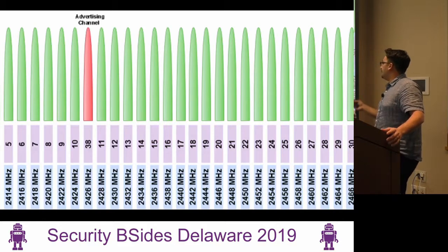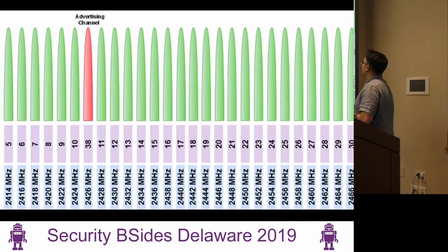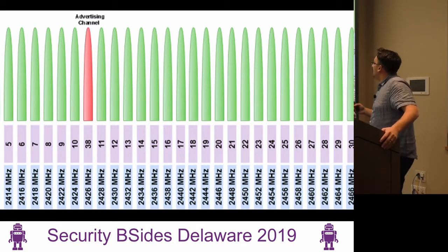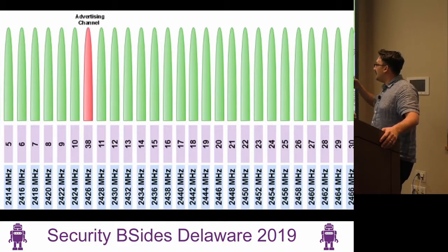What's interesting about this is if you look at 802.11, you'd go into your router and say, this is channel 11 for argument's sake. You would change your router to channel 6 because you can notice that everyone in your neighborhood is using channel 11, and you want less interference. With Bluetooth Low Energy, all these frequency channels are fair game. It's up to the engineer in their code to specify how they're going to hop around these channels. So during the connection request that the advertising channel does, there will be information about what channels are going to be used and what algorithm we're going to use to hop.